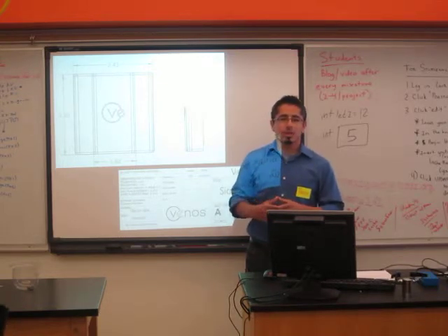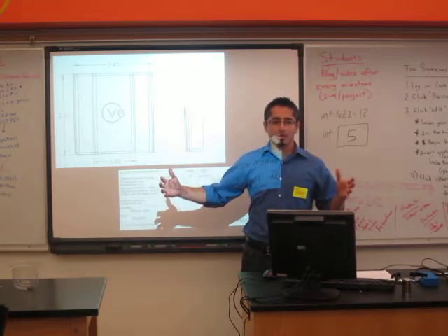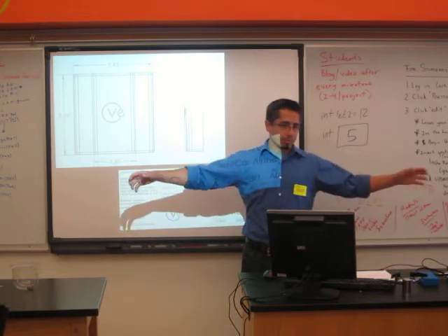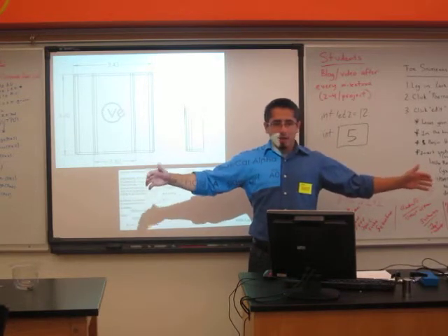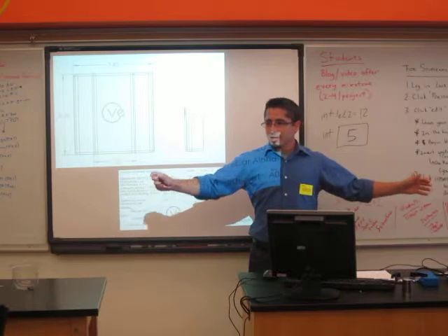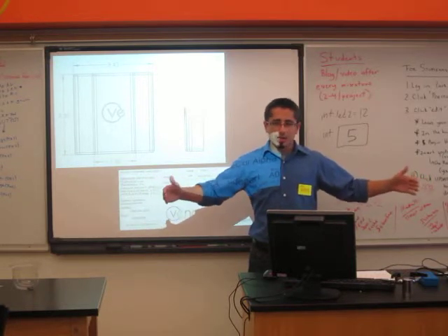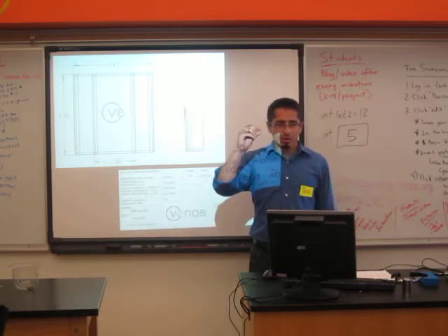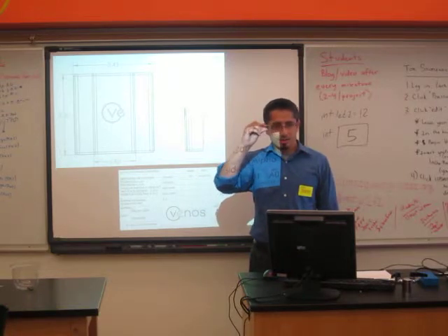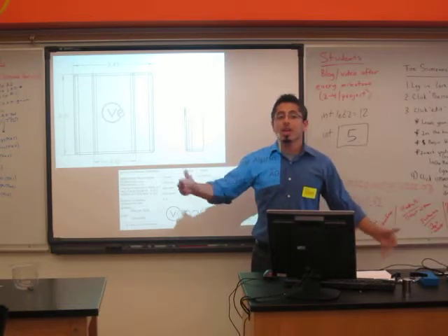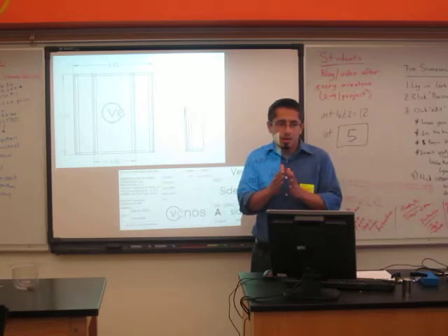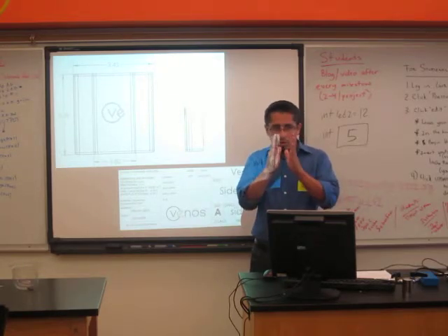So if I'm building something, I'll give an example from the other day. I'm building a house, and I'm laying out my beams on the floor. I'm going to say it's around 42 feet plus or minus a couple inches. It doesn't need to be too precise. Do I need to get it down to 0.001 inches, which is less than your human hair? No, and you can't. So you give it tolerance. I'll say, make it 42 feet plus or minus 1 or 2 inches.